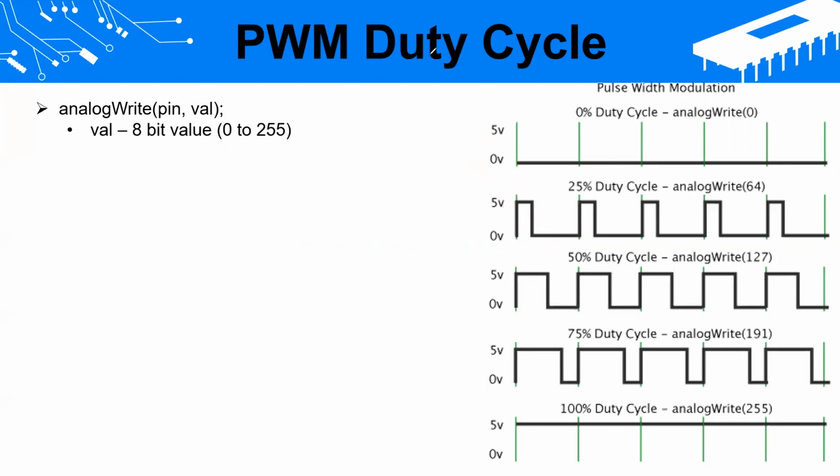For that we are basically using analog write. So we have 4 main types: digital write, digital read, then analog write and analog read. If it starts with digital, there is no issue. But if it is analog and it is a writing operation, we should use special pins. We call those pins PWM pins. We have a set of such pins on the Arduino board.